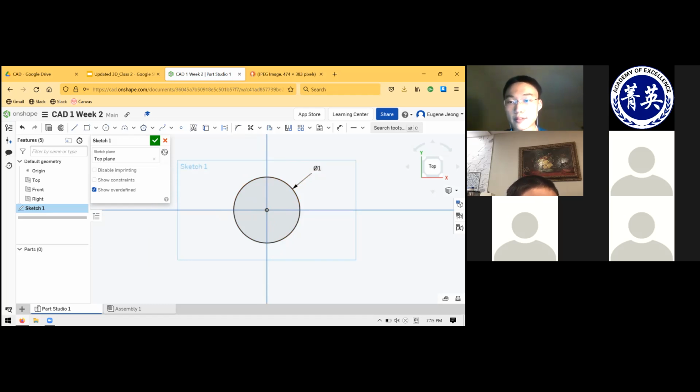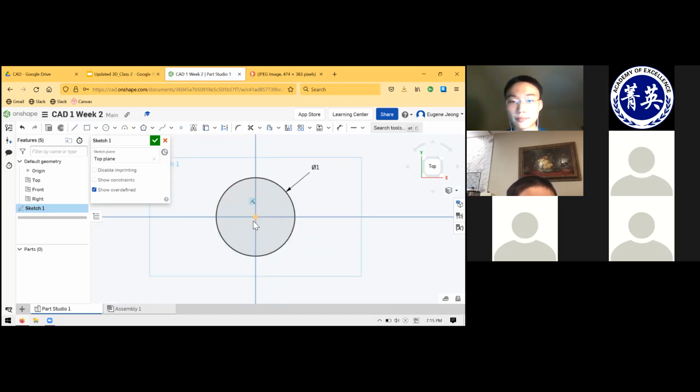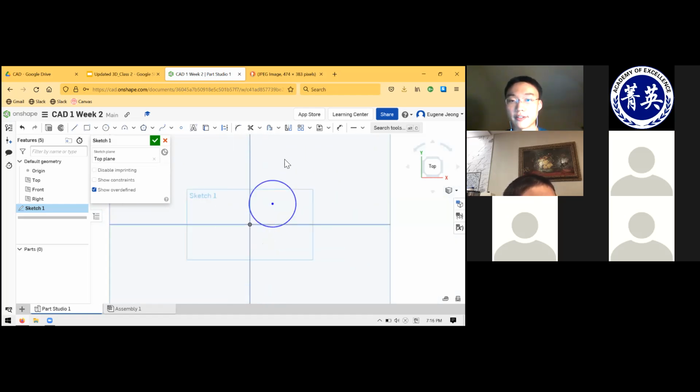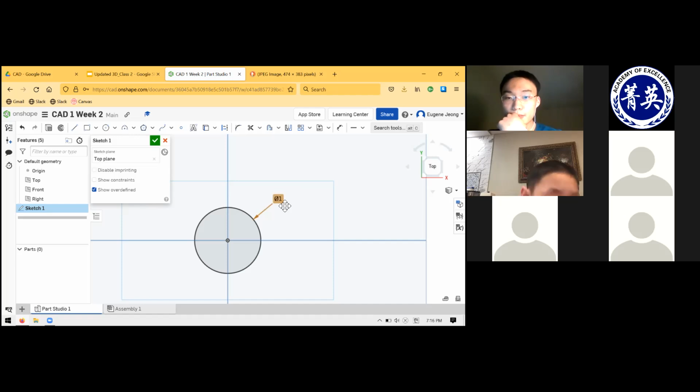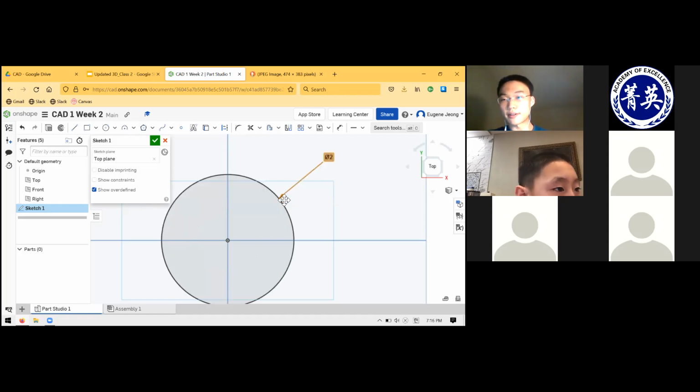And I don't think you can change it after it's in this shape. Are you in the situation where it's something like this? I'm in a situation where it's black. Oh, that's good. Yeah, that's what we're trying to do. Remember, my goal with any sketch is to make everything black. All I was trying to do was change what you were doing, but I typed it into 2 instead of 4, and then it turned black. Right, so I think there's no problem there. As long as your circle is centered here on the origin and you have a dimension, it being black is what it should be.